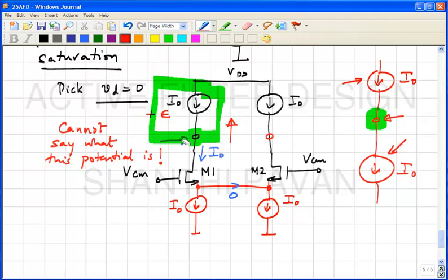So, if this potential keeps rising because epsilon is greater than 0, what will eventually happen? The current source, which is made using PMOS transistors, will eventually have the lower terminal whose potential will start to approach the potential of the upper terminal, and the corresponding transistor will go into the triode region where it no longer behaves like a current source. Does that make sense?